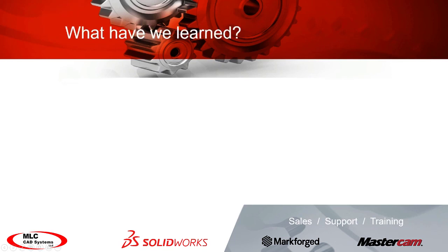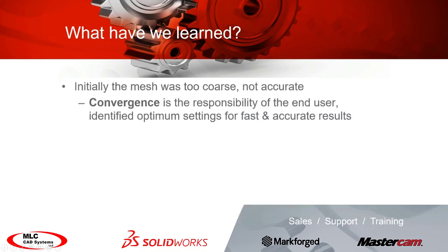So what have we learned? We've learned quite a few things about beer and freezers, but the main thing is the three-step process that you always want to follow whenever you're running a computer simulation. Converge the solution. You need to make sure that the mathematical setup, the mesh, and the settings of the solver are going to give you good optimum results, and there's a pretty easy step to reach that convergence.